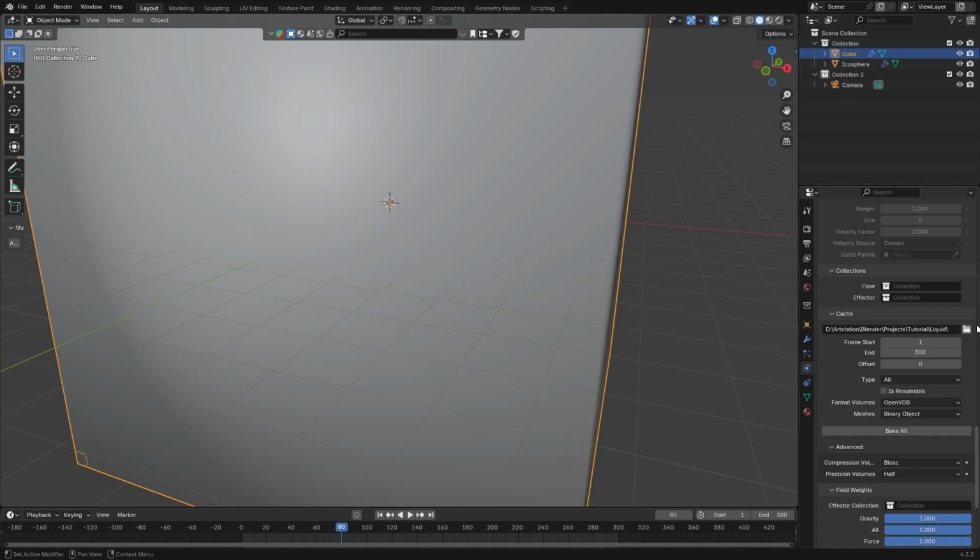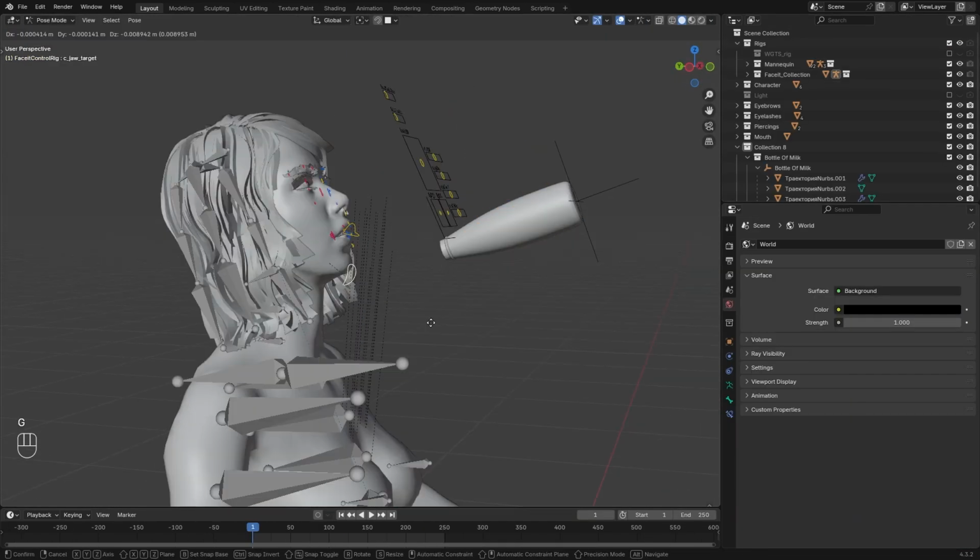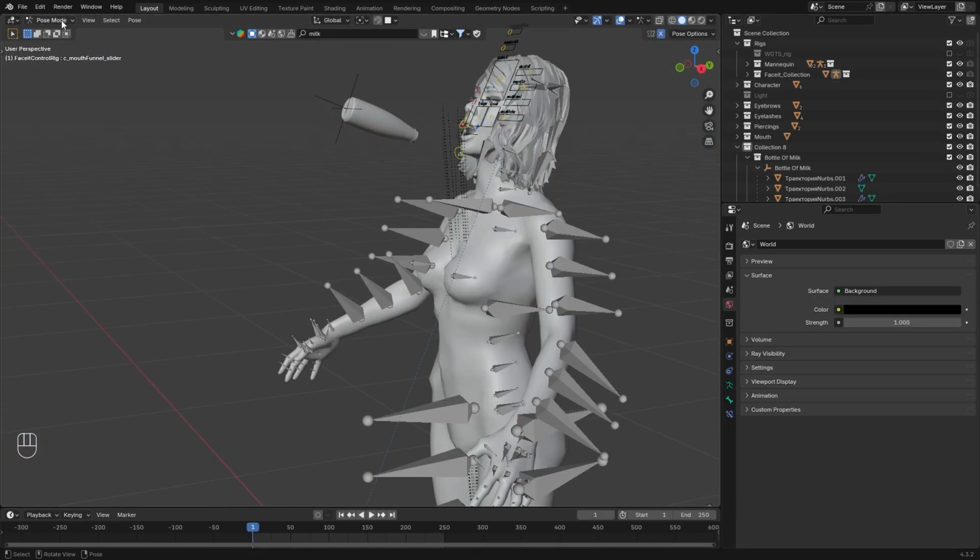If you're creating an extremely detailed high-resolution simulation where the division rate is 256 or above, then be prepared for a baking time around a little more than eternity. Depends on your hardware, but it's definitely going to be an extremely time-consuming process. Now with all that in mind, you can create your own fluid simulation easily now.